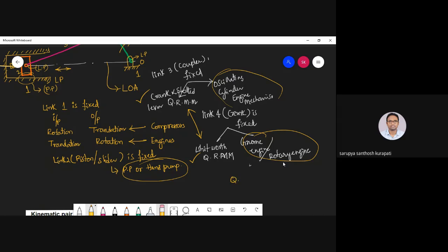Figure, yes. So between these two, we discussed the quick return ratio. What is the quick return ratio? Beta by alpha. Here the quick return ratio is always greater than or equal to 1. So this is about the quick return ratio, and we also discussed the stroke length. I'm just denoting crank and slotted lever as 1 and Whitworth as 2.